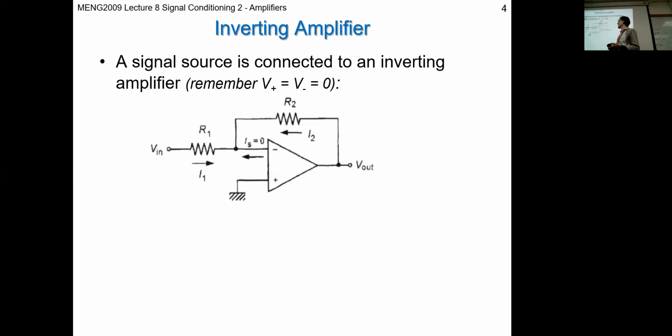So with those conditions in place, we can start to construct the governing equations for this little op-amp circuit. And we know for a start that we have no current flow here. And that means that if we have a positive voltage on the input side, here, which is connected to a sensor, and some input resistance, then there'll be a voltage drop, which means there has to be some current flow, right? Because V equals IR, so I equals V upon R. Therefore if you have a positive voltage and a positive resistance, you have some current flow. But current here is 0.